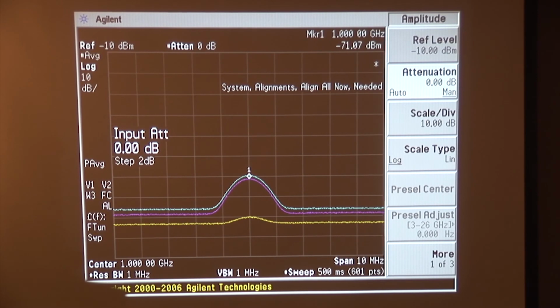So again, people think not only can you read the noise figure off the spectrum analyzer display directly, but now they'll really be convinced that you have superpowers, because how did you do that? Takes years of training and practice. So no, I just twiddled the attenuators until when I turned on the amplifier, I saw it rise 3 or 4, maybe 5 dB above the noise floor I had before. I'm like, okay, that's good. That's right where we want to be.